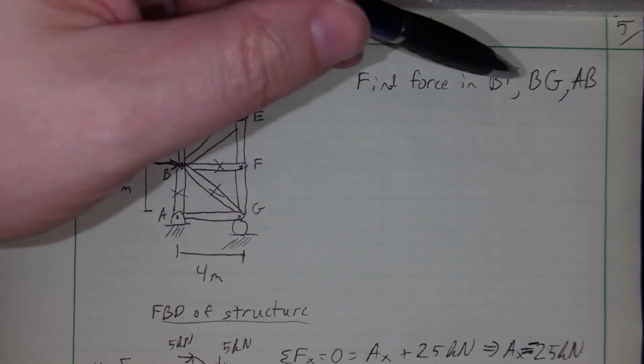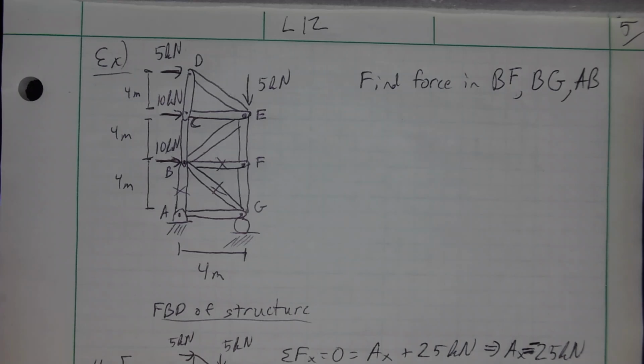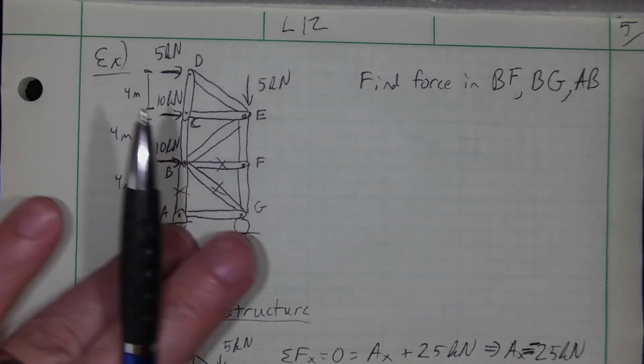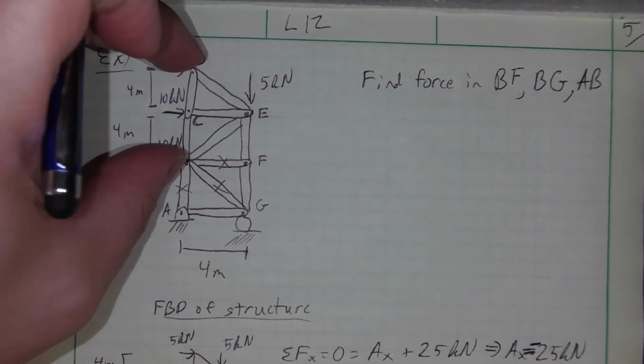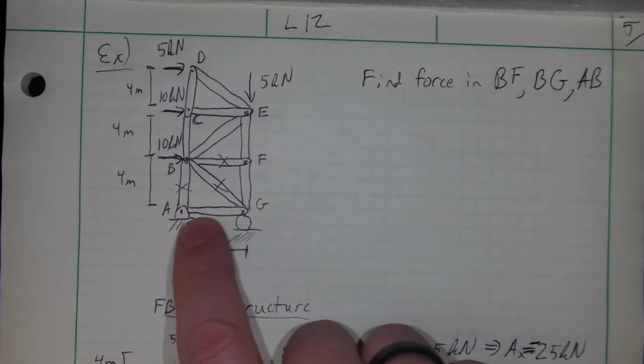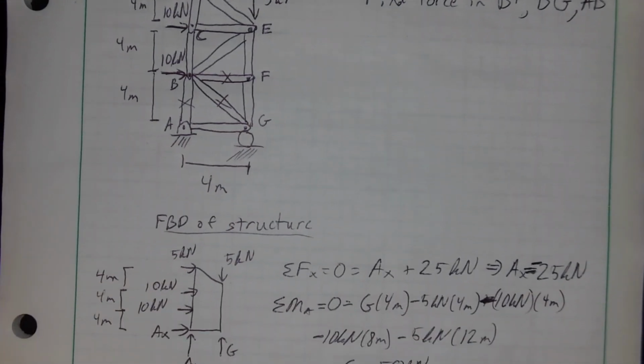We're trying to find the force in these members. Do the reactions do anything for us? Well, honestly, I'll be honest with you. What you could have done is you could have taken a section right here, and you wouldn't even need the reactions. You could just analyze this top part of the truss, and the reactions don't even apply down here. We might still do that, honestly.